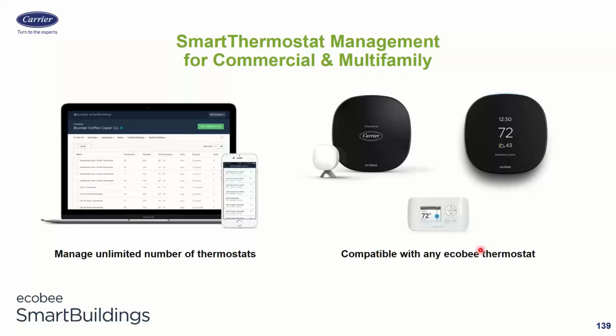But when I put the 22nd stat on there, it crashes my account, locks it up, and I have to beg somebody at Ecobee to unlock it. And then they say, why do you have more than 15 stats on there? So if you have more than 15 stats at a house, I would say make two accounts for them. One for the west wing, one for the east wing on the giant house.